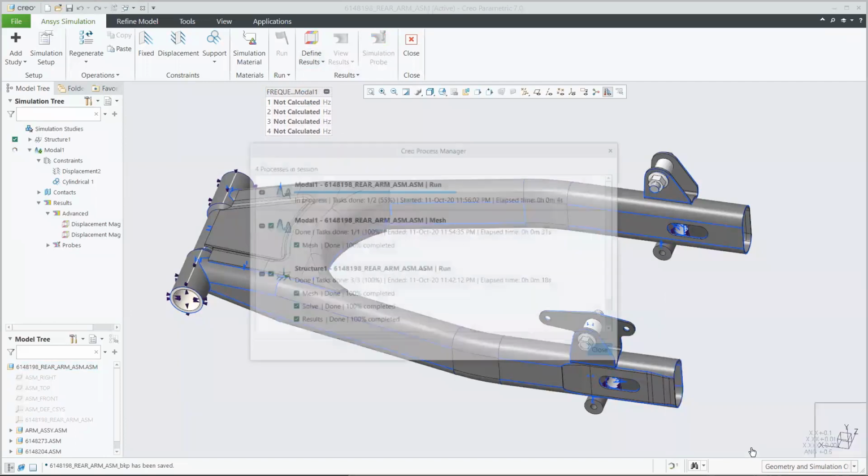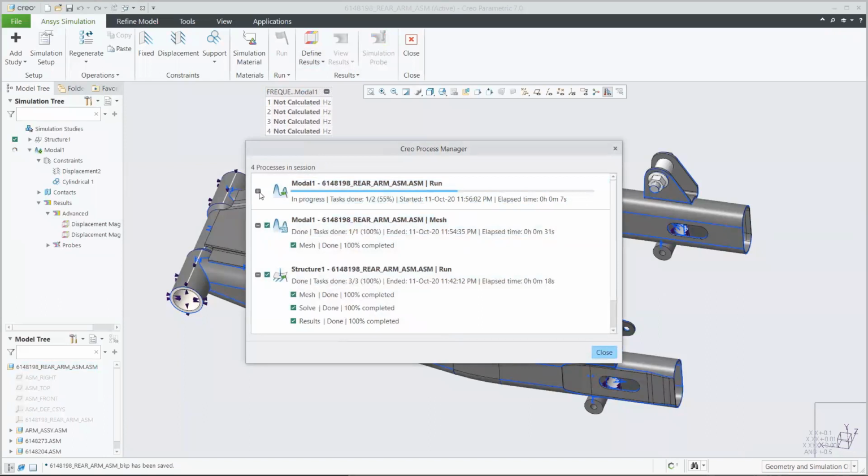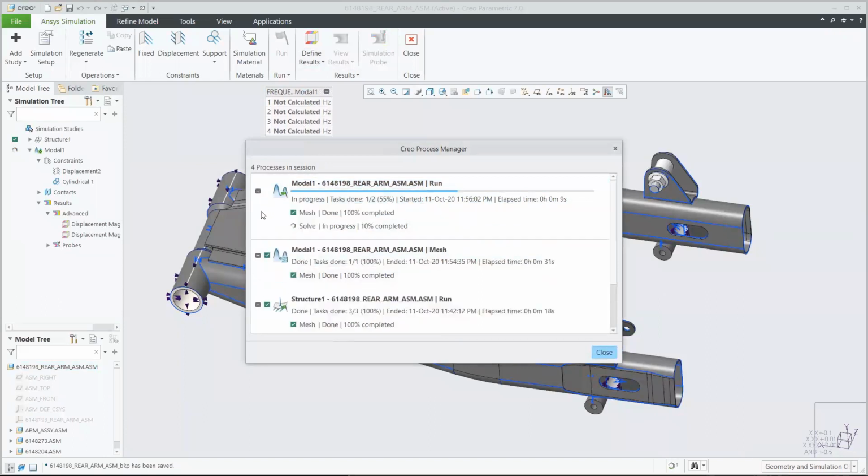And one thing that I'll mention is that, in really looking at the model, you can see that this is closer to being finished. If you were running something like a model that's closer to the early stages of the design process, you'd more than likely be running with something like Creo Simulation Live, much more useful and really a bit faster to go through and get those types of results back. But as you start to get further on in the process and as you want to get more validated and really looking to get those convergent results is where you'd want to turn to a tool like Creo Ansys to get some of those back here. But each really do have their very strong capabilities and their particular use cases they play well into.